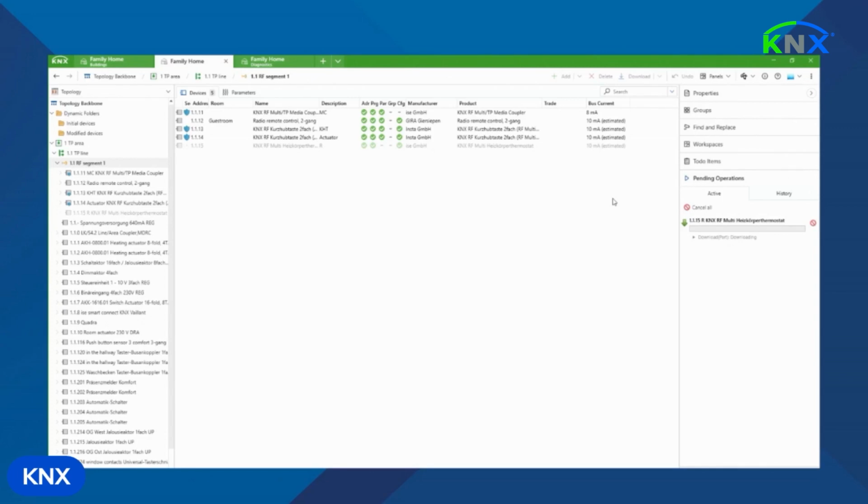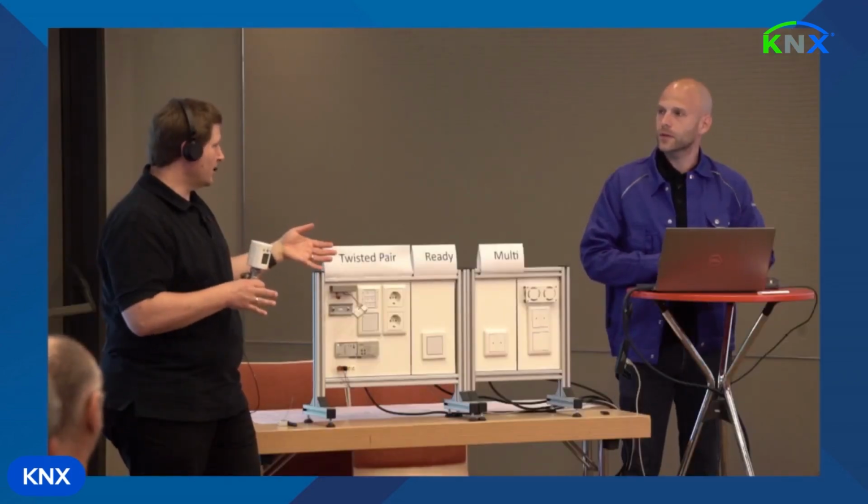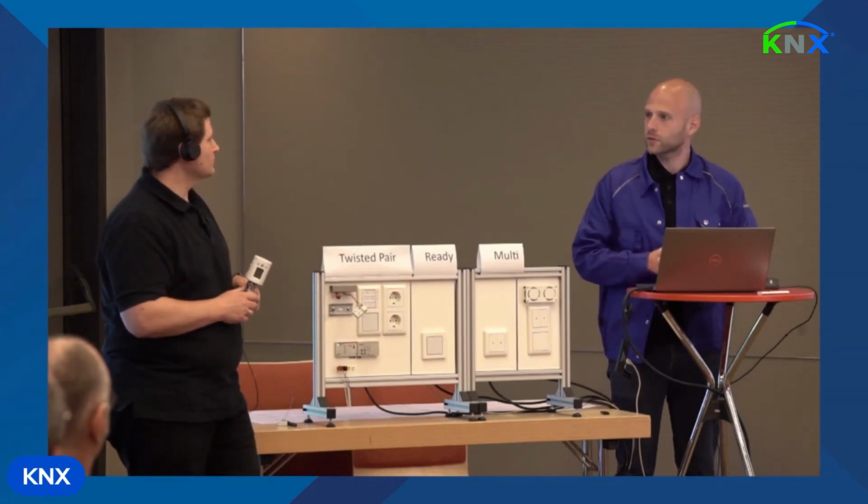If I had more USB interfaces for RF, could I program more devices at once? Not inside the same segment. Okay. It's like with multiple IP interfaces. You can do this in parallel if you're addressing multiple lines. Yeah. There would be collisions otherwise. Topology segments, exactly. But ETS would take care of that for me.